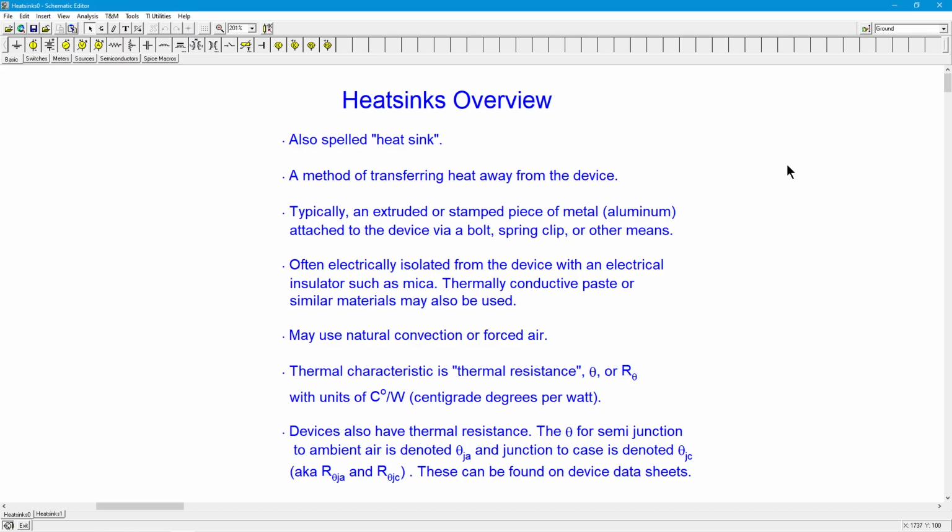In other words, a fan. And very often, in a case like an audio amplifier, that fan will be thermally controlled. In other words, if the power dissipation is not very high and the transistor is not getting very hot, that fan will be at a low speed, or maybe it'll be off. And then as it gets hotter and hotter, we speed up the fan to get a greater volume of air across there to remove that heat.